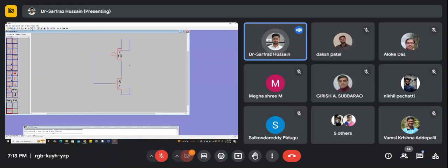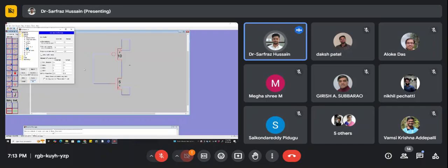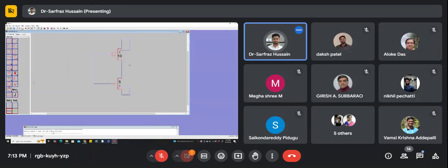And here you also have an option for the grid preference. Now, if you go for the grid preference, here you can put, instead of 0.5, you can put it as 0.01, so that you get a better resolution basically.